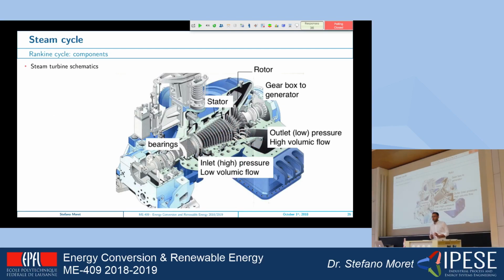If we look at the components, you might have seen, if you have passed by the mechanical engineering department at EPFL, you have a big turbine there, right? That's a steam turbine. And it works with a principle which is basically this one. You start from having an inlet at high temperature and pressure, then the steam is expanded in the turbine. By expanding the steam, the pressure reduces, the volume increases. That's why you have an increase in the section of the turbine.